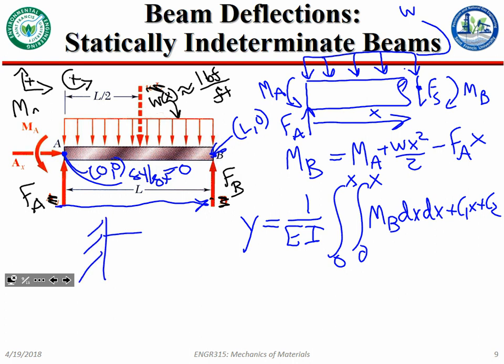We said that's the model of the beam. So this side cannot rotate. That's why there's that reaction moment there. So we said this side is fixed. Because it's fixed, it's stuck to that wall. The section at that wall is fixed to that wall, so that section right at the wall is parallel to it. That means the neutral axis is perpendicular at that point. So we have 3 places where we can specify a boundary condition. How many unknowns do we have now?